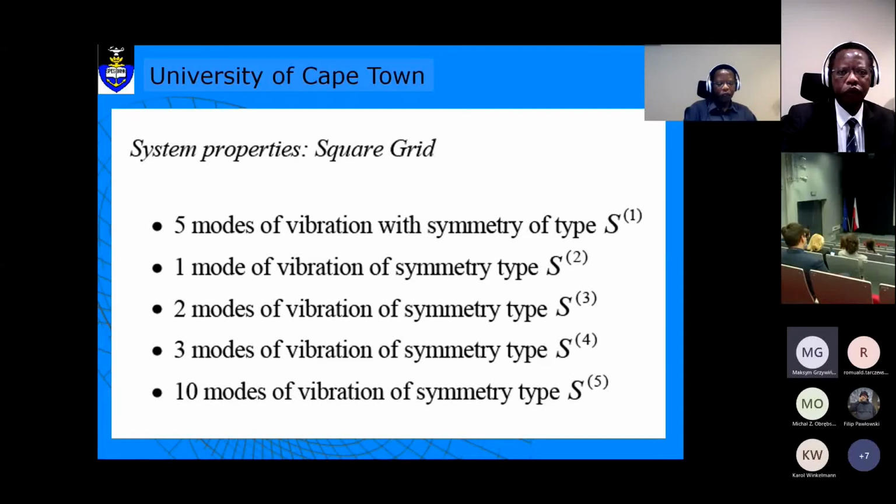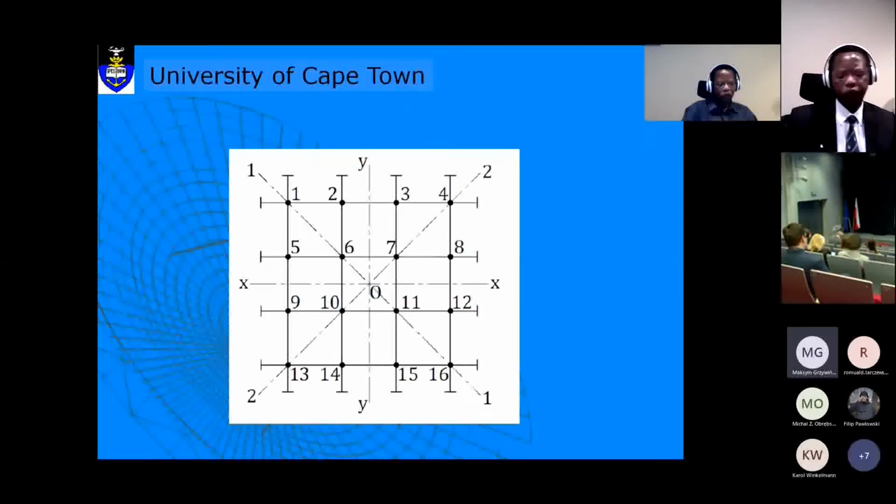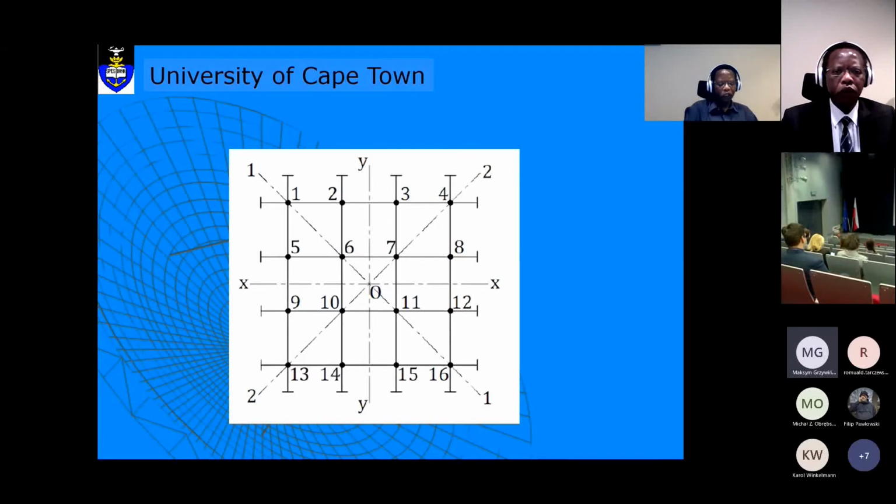To show the results of subspace modes more clearly, let us consider a single-layer square plane grid with 16 nodes experiencing small vertical motions. The square configuration belongs to symmetry group C4V, but we will use the simpler group C2V for the analysis. Applying the 4 idempotents of symmetry group C2V to the 16 nodal freedoms of the grid results in 4 basis vectors for each subspace, which when plotted look like this.